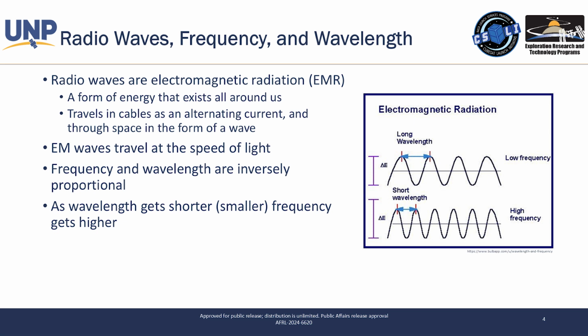Typically speaking, the lower your frequency, the longer your wavelength, the easier it is to get it to travel a further distance. But you're also going to be limited a little bit because, unfortunately, at those low frequencies, a lot of people have grabbed up pieces of them. When you communicate over an RF carrier, you're going to have to license not only the frequency that you're transmitting at, but the bandwidth that exists there.